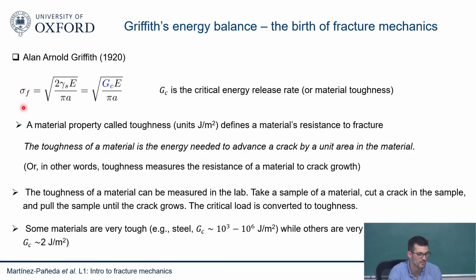If we measure the critical load, then, this is for a semi-infinite plate, so one will have to do experiments with a very large plate, as Griffith did, relative to the crack size. But for other materials, we can also come up with expressions like this one. There will be a geometry factor somewhere, and so we can relate the failure strengths to some critical energy.